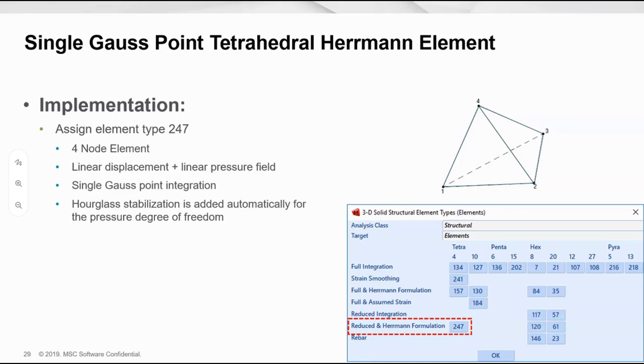This is a completely new element, and of course, it is a four-noded element, linear displacement plus linear pressure field, because of the single Gauss point integration. We also added hourglass stabilization for the pressure degree of freedom for this one.